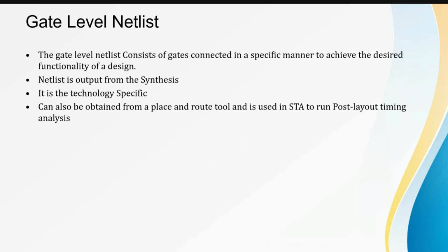And for the netlist, the STA will be done in two different stages: one before PD and one after PD. When the STA is done before the PD, it's a pre-layout STA. At the sign-off stage, post layout, after doing the PD, the STA will also be done.